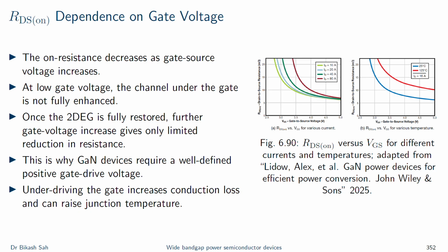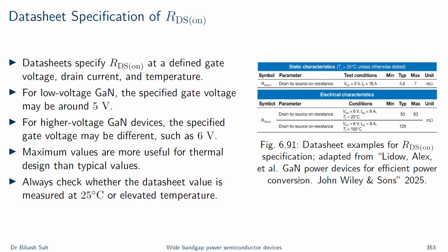Right. So if you remember, the driving voltage in the case of a MOSFET was quite wide. It was somewhere in the range of 12 volts to 21 volts, depending on the type of manufacturer, so silicon to silicon carbide. But in the case of GaN, it's very small. In general, for an E-mode device, it ranges from 3.3 to 5 to 8 volts maximum. This is what we apply in there.